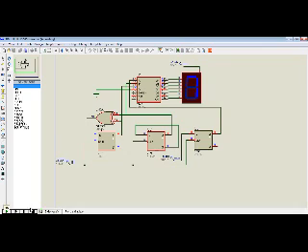Yeah, so the connection to the clock was not intact at this point. You can confirm now it's counting 1, 3, 5, 7, back to 1. And that's our counter that counts odd numbers between 0 and 7 using the D flip-flop.